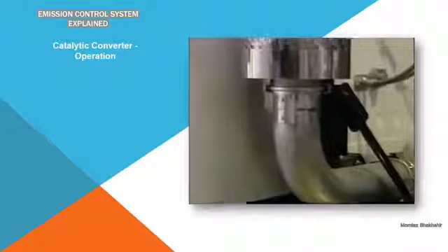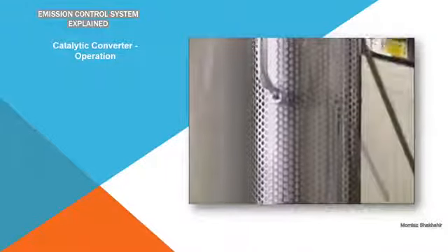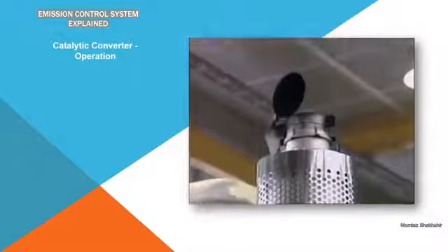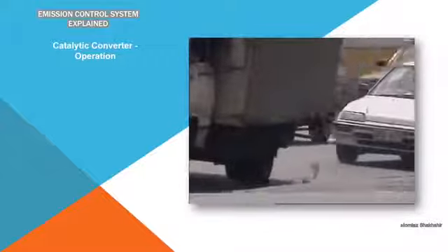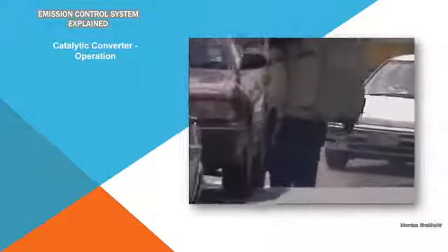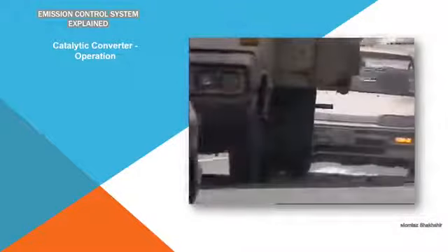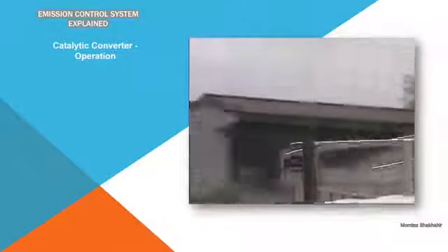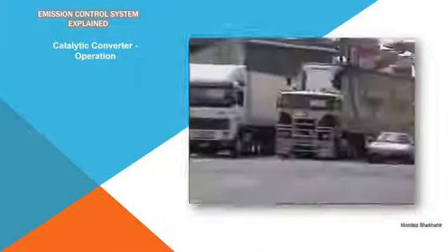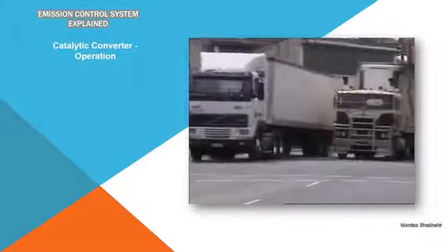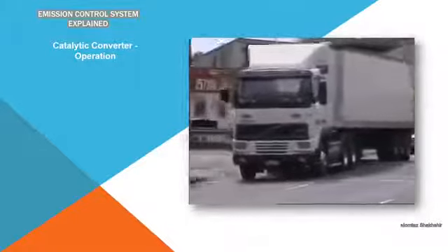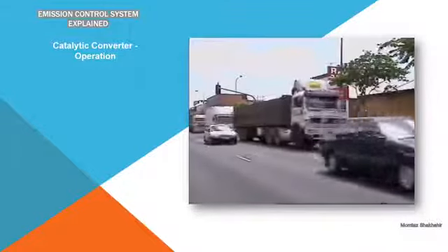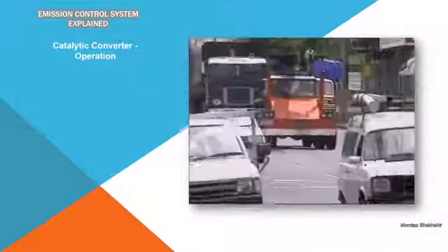Diesel engines are usually low in carbon monoxide and hydrocarbon emissions, though some do emit high levels of the oxides of nitrogen. The main problem with diesel engines is the emission of particulates, minute particles of carbon, visible as black smoke. Most diesel engines of heavier vehicles use electronically controlled injectors. This has reduced considerably the emission of particulates and oxides of nitrogen.